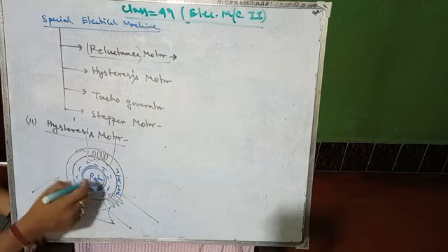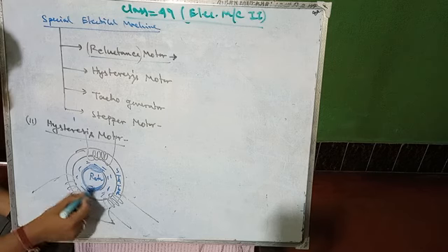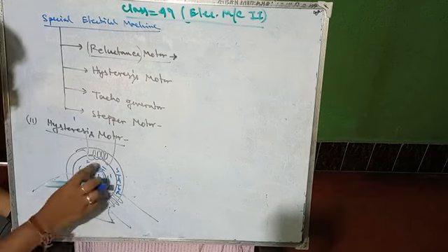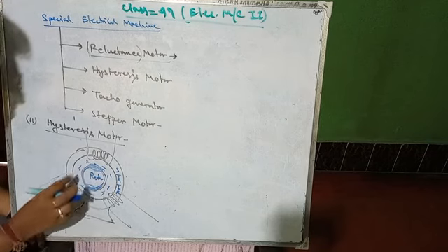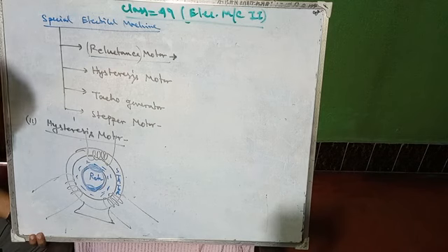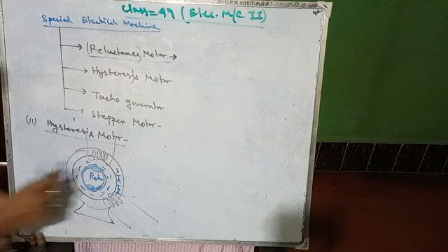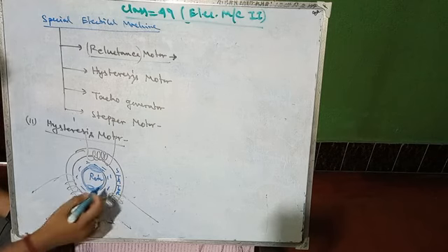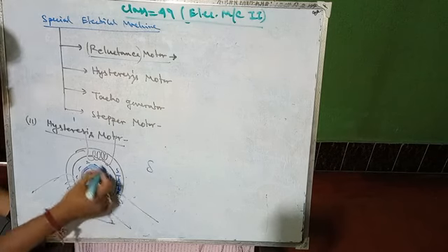And a pair of corresponding rotor poles are generated. There will be a generation of instantaneous poles inside the rotor, and these poles are generated lagging by the acute angle delta from the rotating magnetic field.